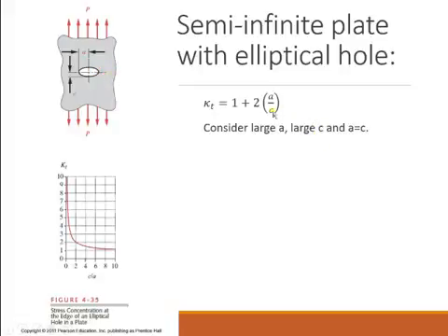It turns out that the two parts of this ellipse, A and C, are going to contribute to my stress concentration. Let's think about what happens when A becomes very large. When A becomes very large, the notch has now spread all the way across the beam, and K, the stress concentrator, would be huge. Here it is graphed.